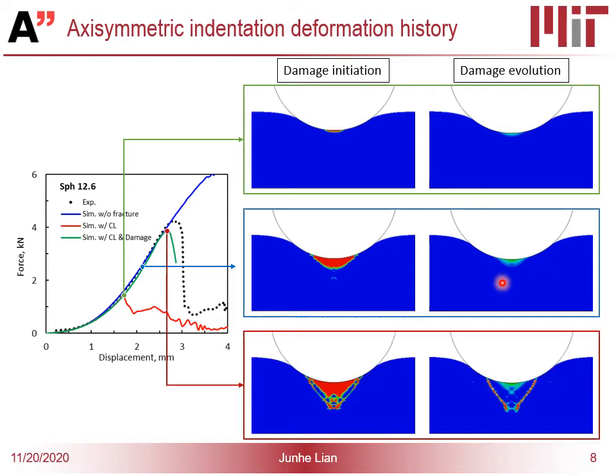Until we reach the final point, a lot more elements have reached damage initiation, and you can probably see these two lines, which finally lead to the final fracture. These are the clear shear fracture lines. They are the cause of the final fracture, actually not all the damage right below the punch.